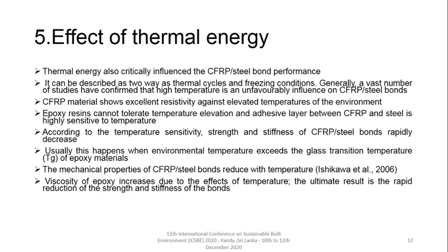Carbon fiber reinforced polymer material shows excellent resistivity against elevated temperature of the environment. Epoxy resins cannot tolerate temperature elevation, and the adhesive layer between CFRP and steel is highly sensitive to temperature. According to the temperature sensitivity, strength and stiffness of carbon fiber reinforced polymer-steel bonds rapidly decrease. Usually this happens when environmental temperature exceeds the glass transition temperature of the epoxy material.